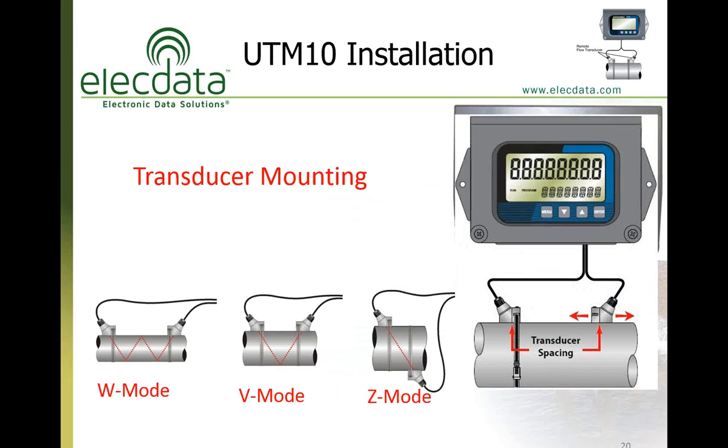There are a number of modes for mounting the transducers to the pipes. One of the common things before we get into the different modes shown is to always make sure that you mount the transducers off on the side of the pipe, between, say, 1 o'clock and 5 o'clock, or 7 o'clock and 11 o'clock. You never want to be at the 12 o'clock or the 6 o'clock position. Avoid the 12 o'clock because a lot of times there's gases or aeration trapped in the very top of the pipe, and in a lot of pipes there's sediment at the bottom of the pipe.